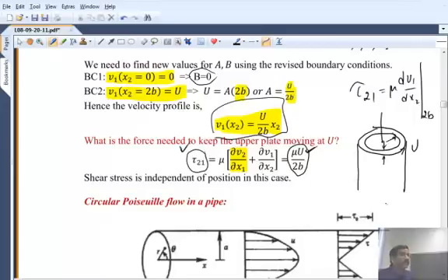To analyze that problem, you could use results from here because it's basically, once again, flow between two thin plates, whereas the bottom plate is the table that is fixed, the top plate is the sheet that is moving. Okay? So if you have to estimate, for example, if you know the density, the viscosity of air, if you need to estimate what would be the velocity of the sheet or how long can it go, things like that, you can get some idea, an order of magnitude estimate of the idea from the solution to this particular problem.